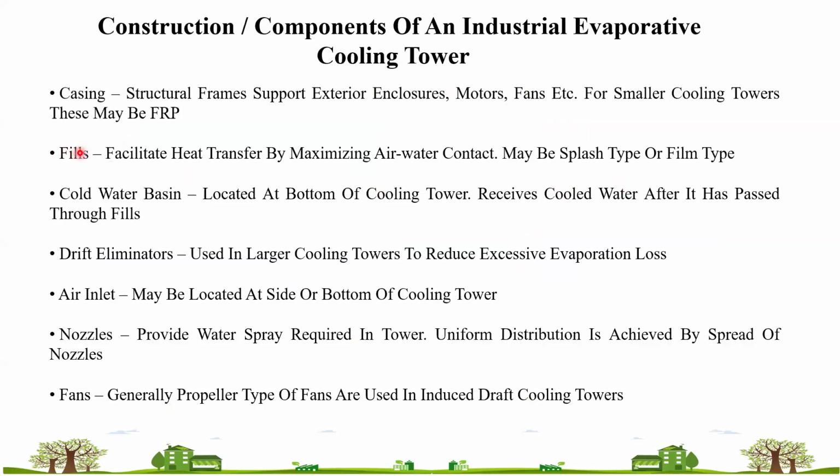Fills are some surface, some medium which provides maximum heat transfer area, and they may be splash type or film type. We can see the types of fill, but they are majorly used to provide maximum heat transfer area. You have seen heat exchangers in your industry.